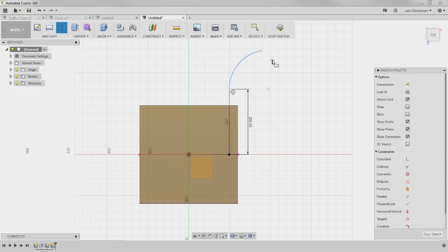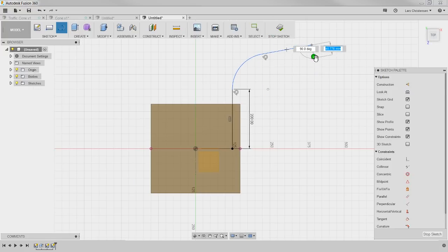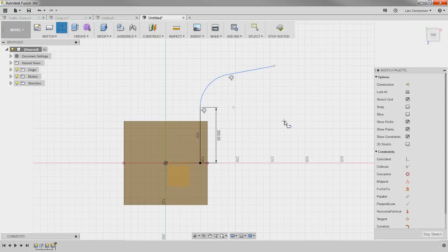We can then draw another line, something like that there. Now, it's best practice to make everything black. So default dimension, maybe we make an angular dimension from here to here. We can make that 80. A radius, 120. And then we probably also need some kind of a length on this edge here.